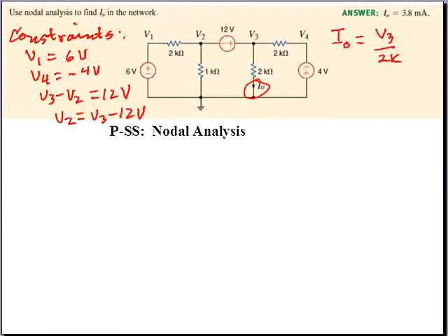We'll be applying the relationship for a supernode in writing our appropriate KCL type equation. This is the supernode with that floating voltage source. We'll label currents positive flowing away from that supernode surface. So we have 4 elements there connected to the supernode, so we'll want to sum those currents to determine the appropriate Kirchhoff's current law equation.